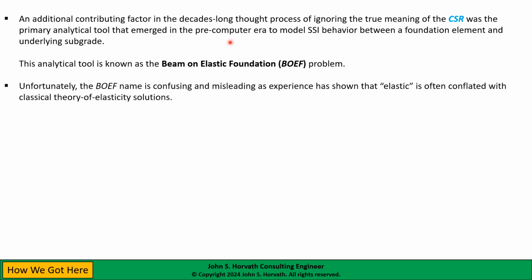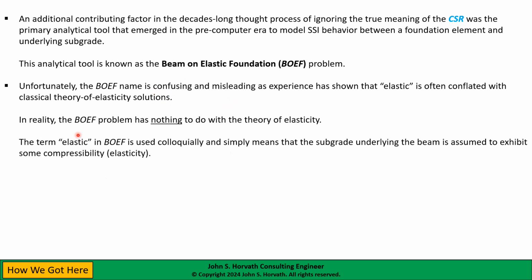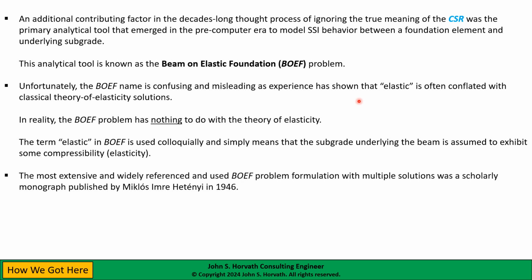Very unfortunate name. I've talked to many engineers and they're confused by this term, beam on elastic foundation, because the word elastic here is conflated very often with classical theory of elasticity solutions. In reality, the beam on elastic foundation problem has nothing to do with the theory of elasticity. The term elastic here simply is used colloquially and means that the subgrade underlying the beam exhibits some compressibility or elasticity, if you will.